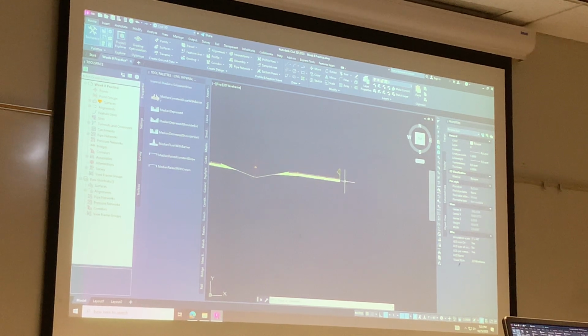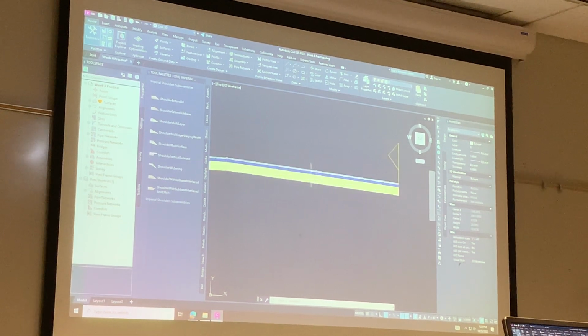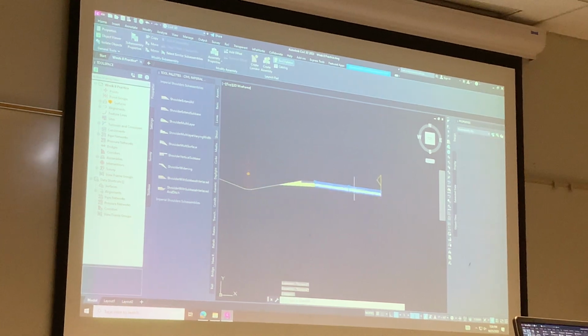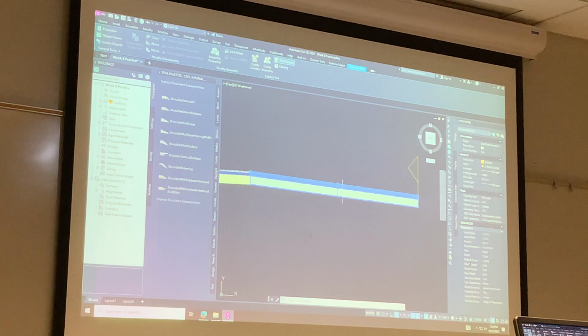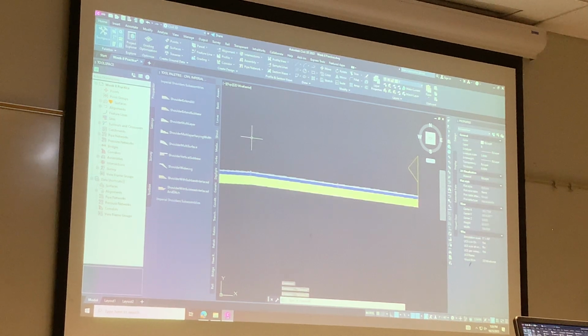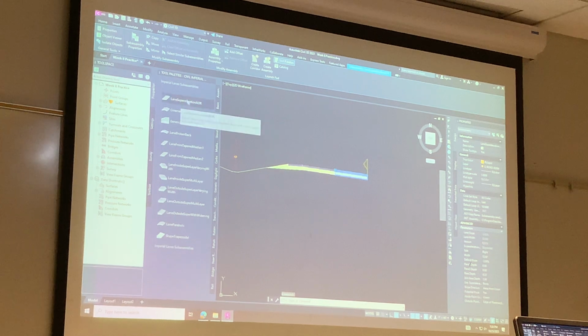Okay, outside of the travel lanes, we've got the right shoulder. So I've already thrown 2 lanes on here. You can do that, or you can do 1 lane and change its width to 24 feet. It means the same thing. Sorry, which one is the one at the end? Like this? Yes. These are the lane super elevation.